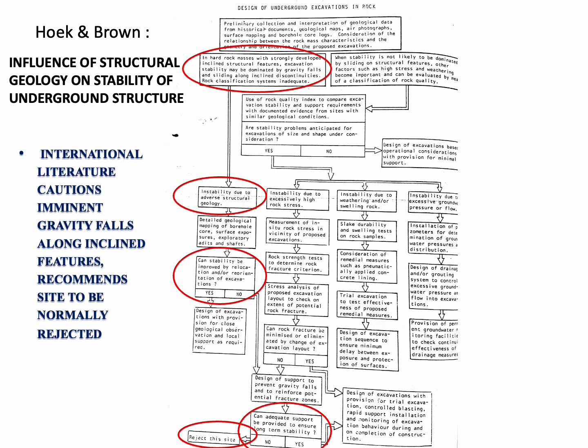If it is yes, then proper designs of excavation, with close geological observation and local support as required, need to be done. But if the answer is no, that the stability cannot be improved by relocation, then design of support to prevent gravity falls and to reinforce potential fracture zones needs to be resorted to.